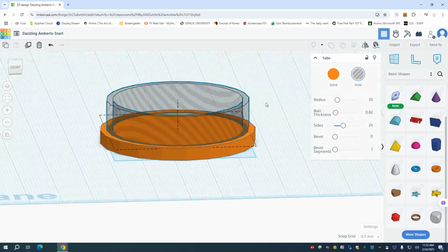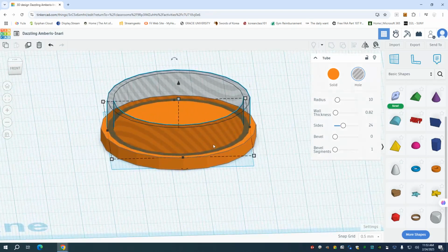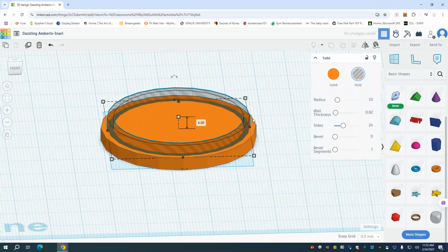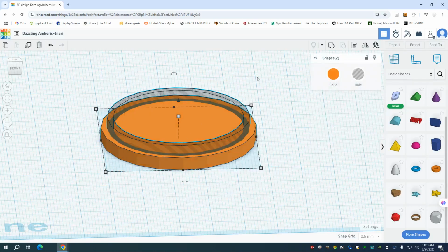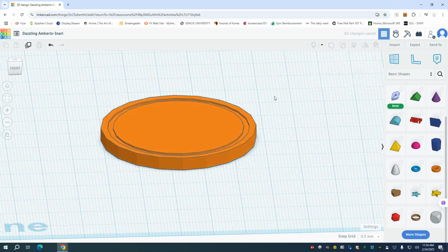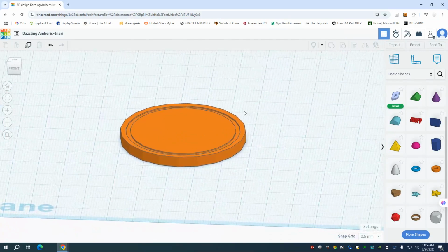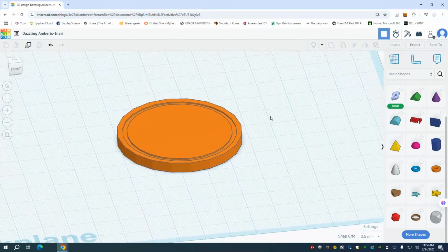Okay. And once you've done that, you can do this one at a time, or you can do it after all the parts are kind of brought together. I'm just going to lower that casually. All right. So now I'm going to do a left mouse selection over everything. And I want to group these together. When I group them together, you'll see that the negative space is now cut out. So TinkerCAD makes it very easy to do things like this.